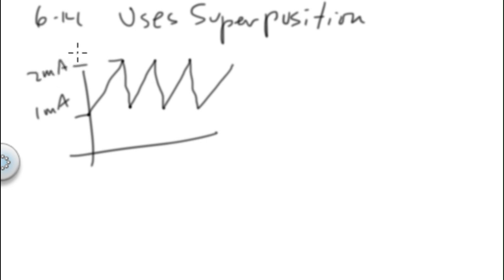And you can do that by observation if you want to, but basically, if you see that this one is contributing 10 volts and 10K, that's 1 milliamp. The other one is 10 volts and 10K, that's the other milliamp. So you got your DC supply right here. This is your DC side, and up here is your AC side, or your time varying side, and that's all you need to see. And that's the whole answer right there.